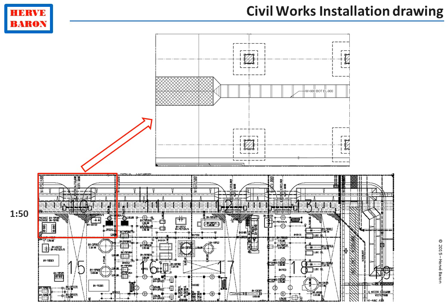Their first revision will be for equipment foundations only. Then they will follow the work sequence for the installation of undergrounds at site, which proceeds from deep to shallow. The next issue will therefore be for the next layer above the foundations, which is the main headers, such as the sewage header and the rainwater distribution header.